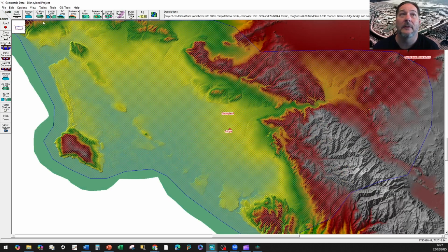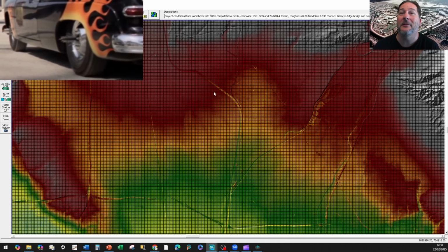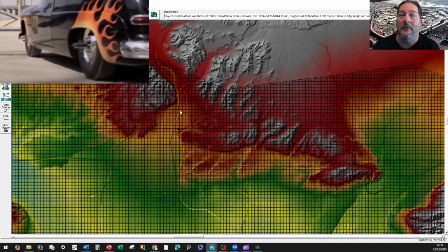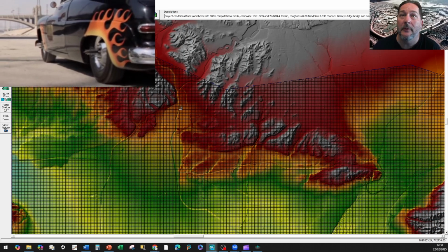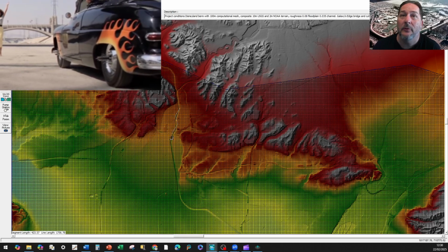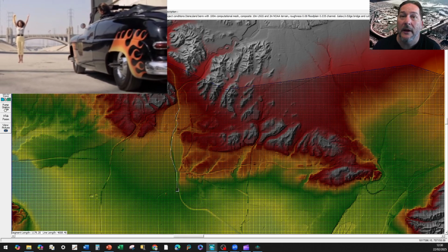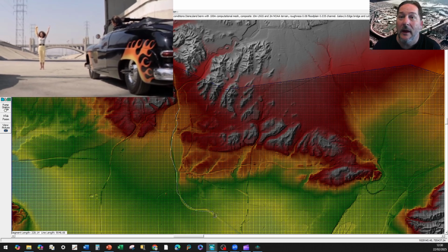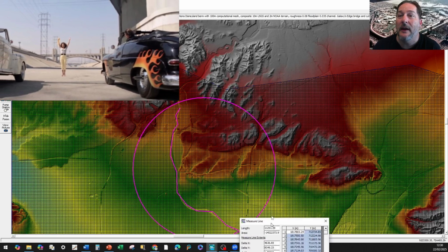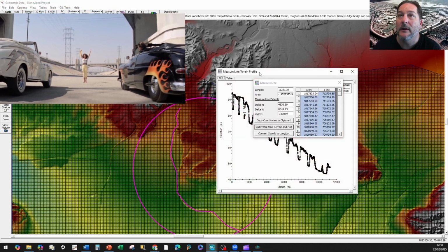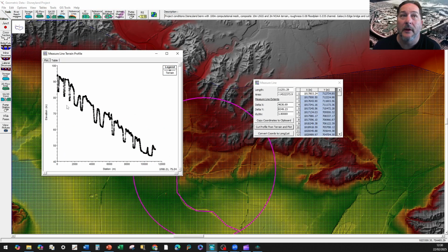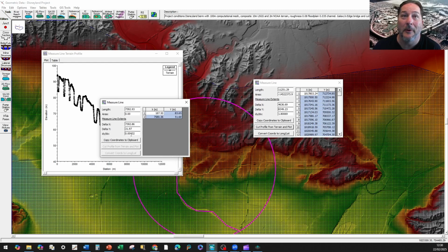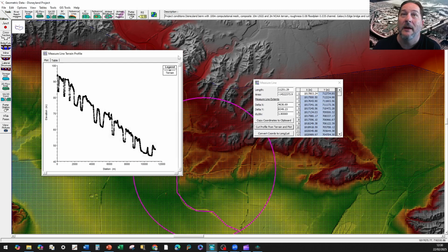But if I look at any of these rivers here, including say the LA River, some of these are highways, and so it's hard to tell which ones are which. But here's the LA River itself. So if I wanted to see what the slope of the LA River was, as long as I'm not messing around too much with the overall longitudinal flow path length by crisscrossing here, then when I double click at the end and try to connect these points with the profile line, I've crossed the low flow right there, and it should be a fairly consistent slope. So if you look right there in this reach of the LA River, right by Skid Row, you're at about 0.43, so about 0.4% as well in terms of your slope.